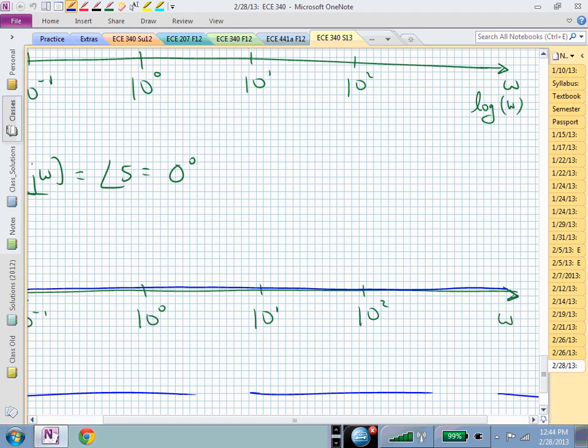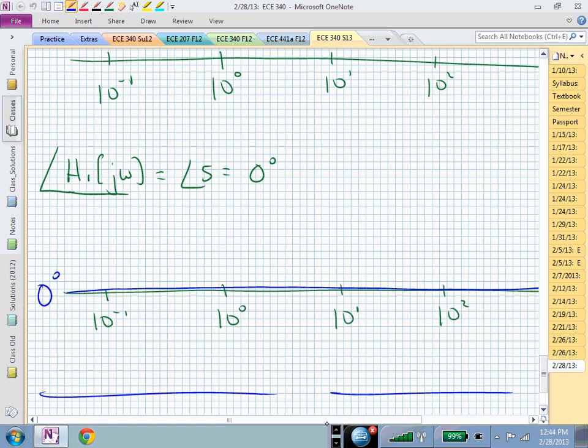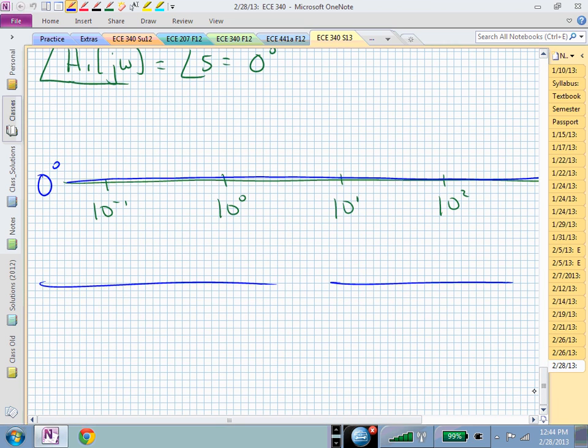And then if you had multiple pieces, maybe at least you've gotten one piece right, which is the constant piece's angle, right? And that represents the phase of h sub 1 of j omega, which we said, for this example, let's just let h be 5. That's the first case of these 4 different possibilities of cases that we can have in sketching Bode plots.